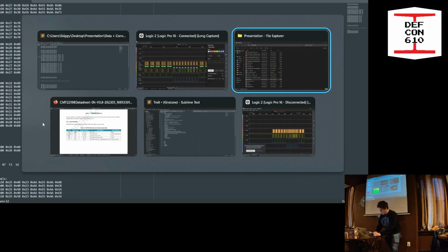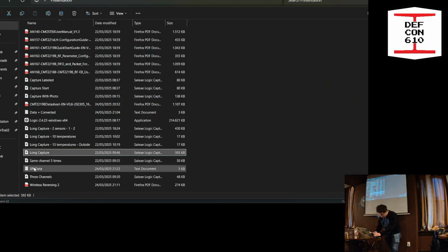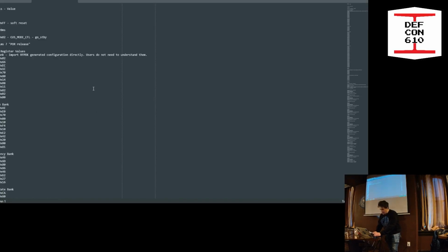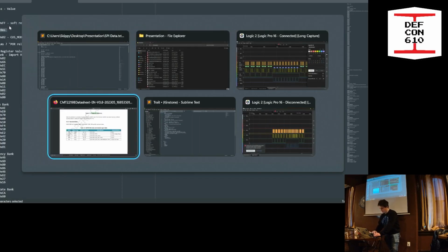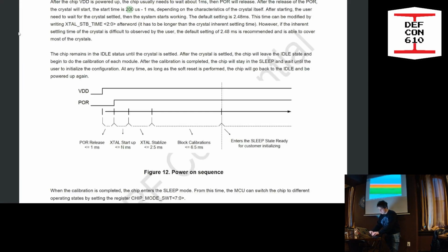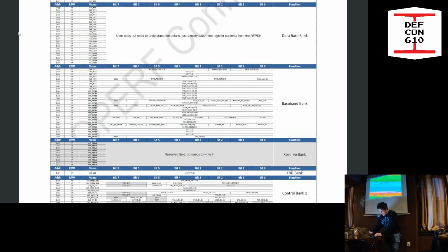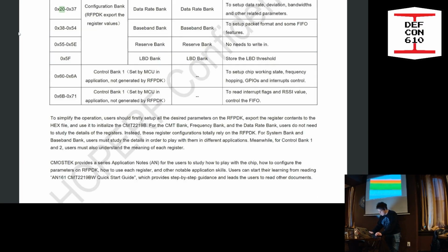So then you start, so you write down the data that's coming in at the beginning. So you see the 7FFF, that's soft reset, wait 20 milliseconds according to the data sheet, which I don't know. Let's see.